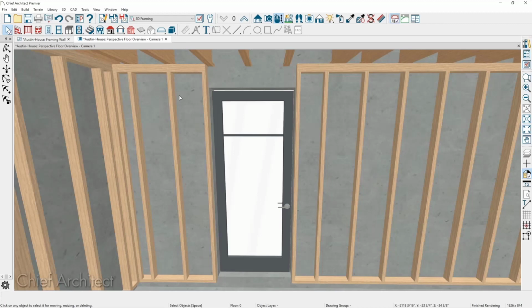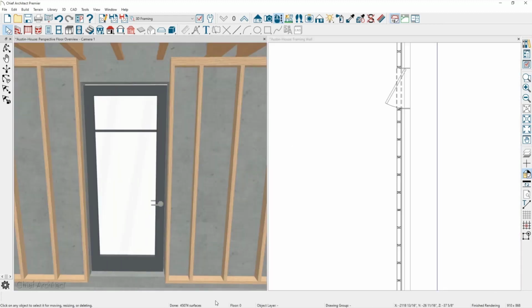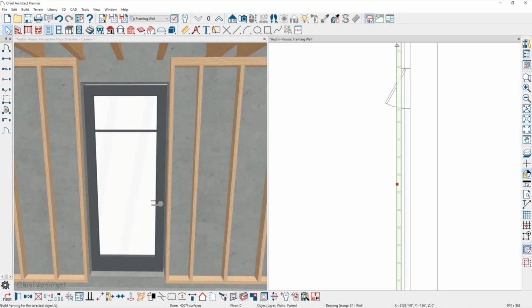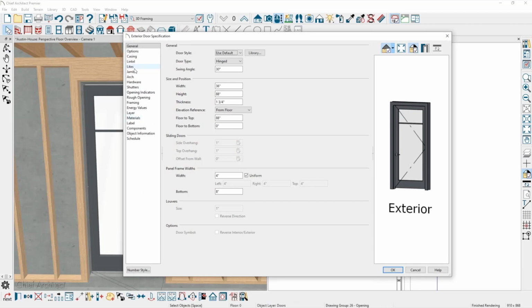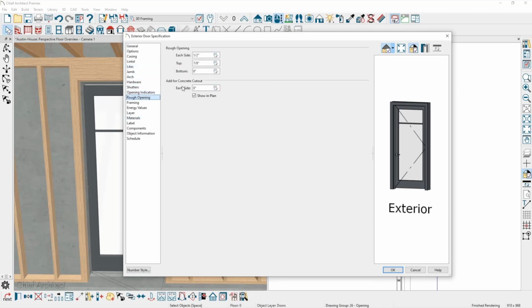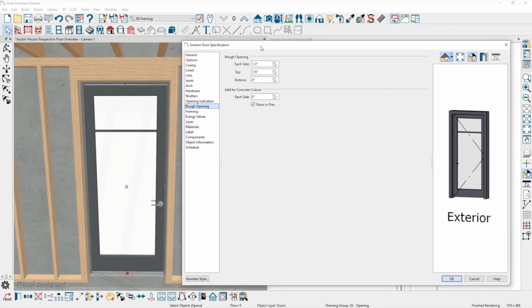It would be very similar to putting a door in one of the standard brick walls that we have, where the door recesses into the framing. The other thing I might try is to modify the door's rough opening so that the cutout gets bigger. That would make it possible to maybe add some manual framing in there. But that's what I do today. Yeah, but I like Scott's idea of getting some sort of framing component in there. It's going to affect the entire wall. That's the only problem. Yeah, I tried that idea with just the door. The problem is it frames all the way to the top and eliminates the concrete.